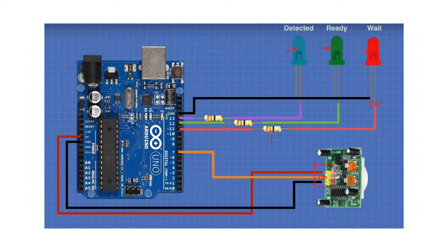So you can see we have put a resistor to protect each and every LED. You may want to ask why this resistor along the way. So you see, the power is coming like this and moving to the red, look at the red LED, but somewhere along the line we have to put in the resistor just to protect it from burning.